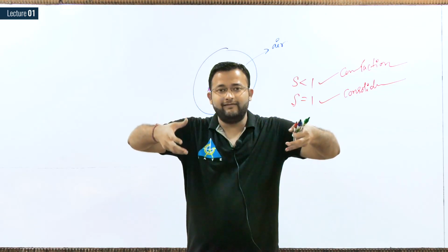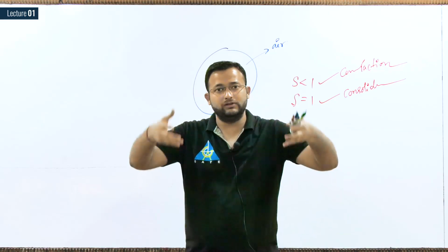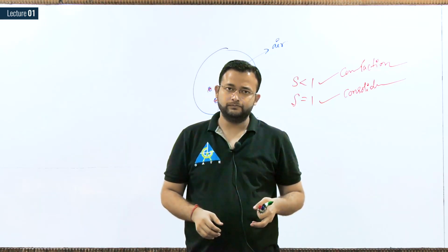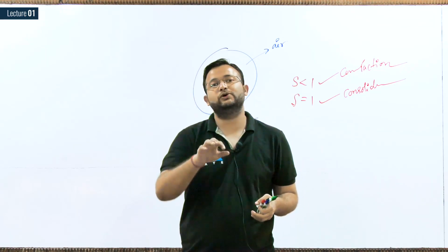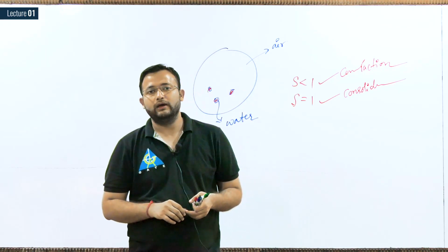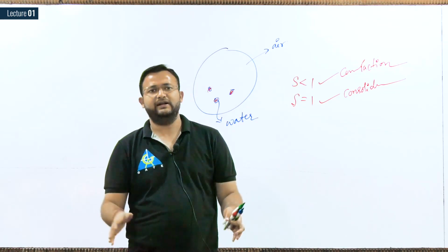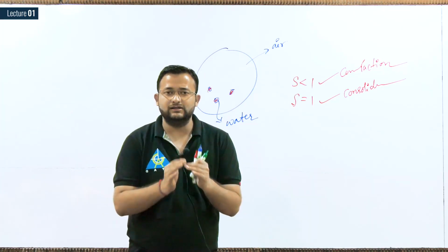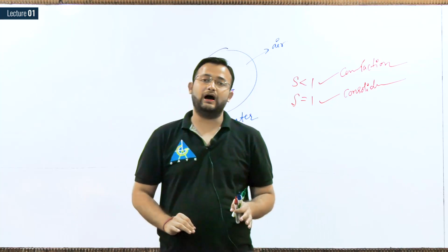Now you have kept one big building on the soil, on your plot. Because of the weight of this building, the consolidation process will start, and it may take 1 year, 2 years, 10 years, 100 years. Slowly water will be dissipated, it can be drained out.